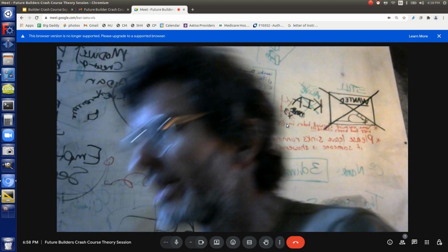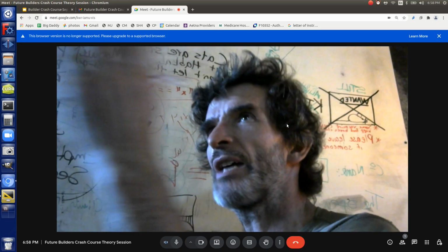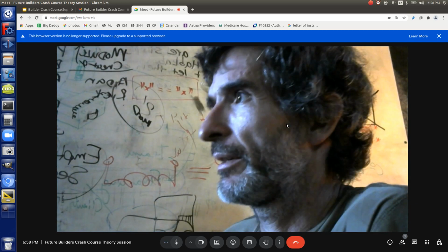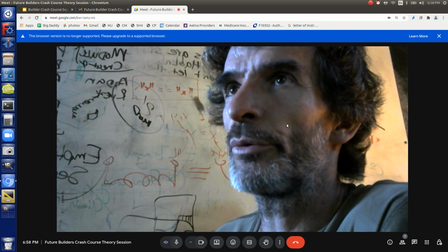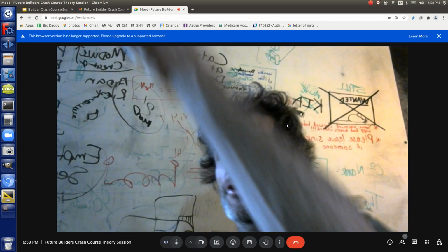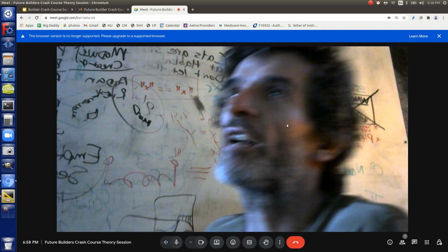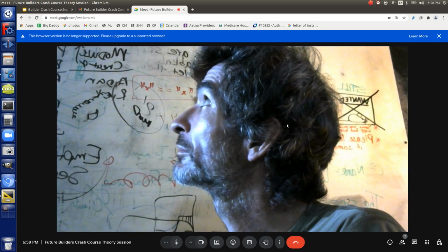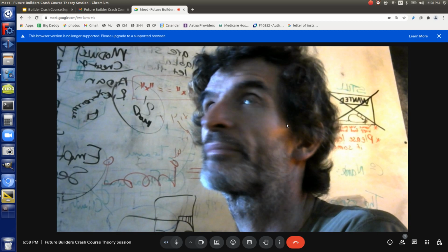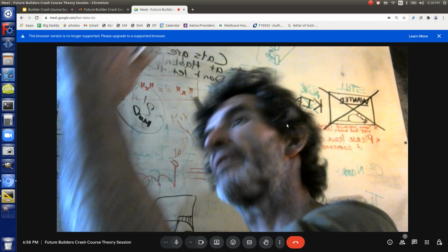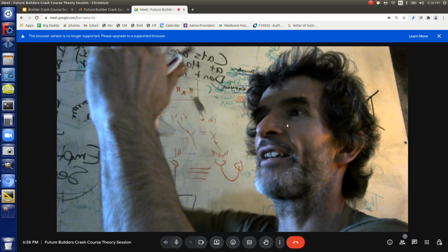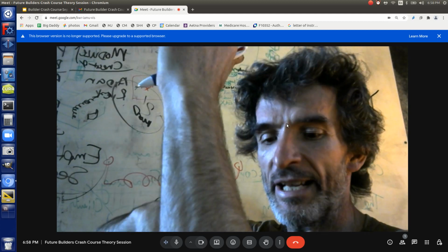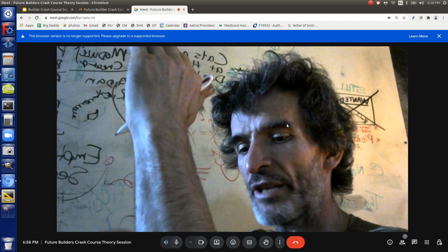But then let's talk about when you got the walls plumb. What's the limit before things start to fail? If you have a vertical stud like that, what's the tolerance for it being vertical? Well, the way you analyze it is if it's off enough, the force is no longer pressing straight down, it's going to want to push off to the side.